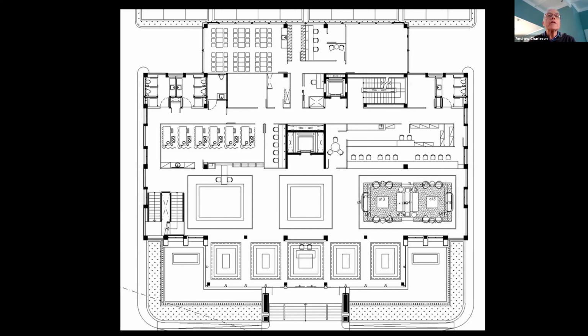What about moment frames in this building? Well, on each perimeter, you could have a moment frame. Like this is about 3 meters, roughly 3 meters. So you could have a column, another column here. That's about 6 meters there. And then about 6 meters to the column and then 3 meters there. So there could be a moment resisting frame along there and also along there to resist earthquake.